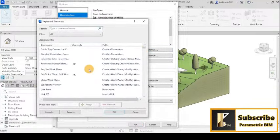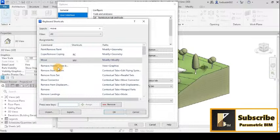For example, if I want to search about move, I will have move, its shortcut is MV. You can maybe remove this or add something else. For example, let's say wall. What is the shortcut of wall? Let's say here wall. WA is the shortcut of general wall ribbon or command.